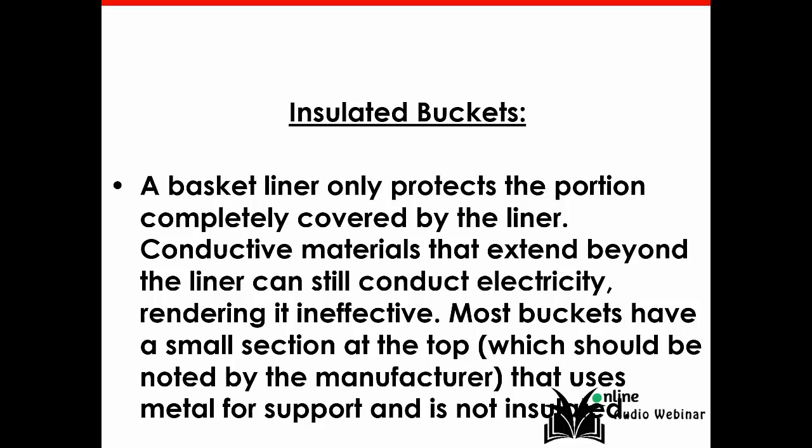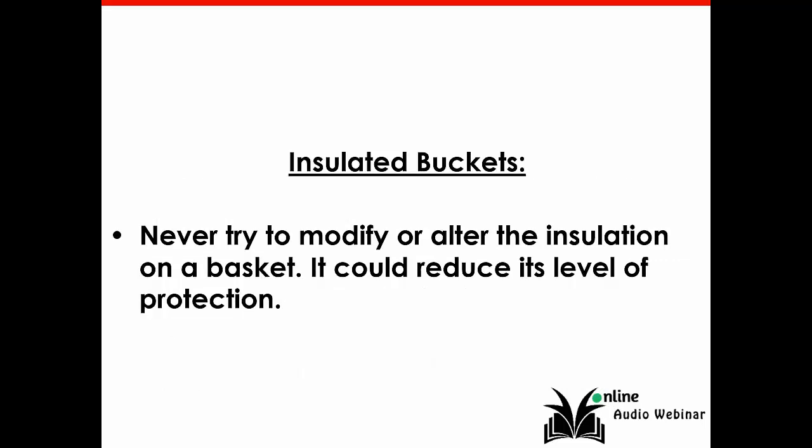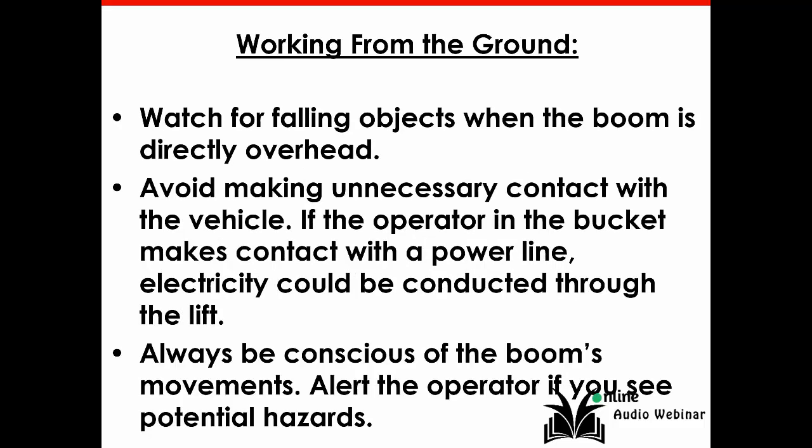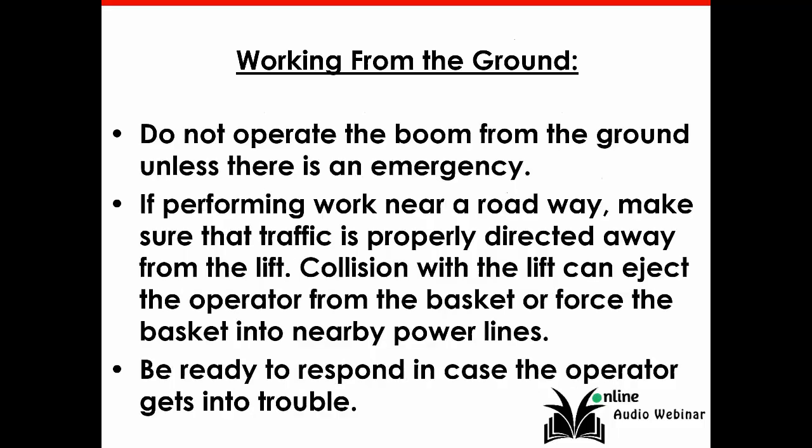So insulated buckets. Never try to modify or alter the insulation on a basket. It could reduce its level of protection. And also from working from the ground. So watch for falling objects when the boom is directly overhead. You want to cordon the area off. Don't operate the boom from the ground unless there's an emergency.